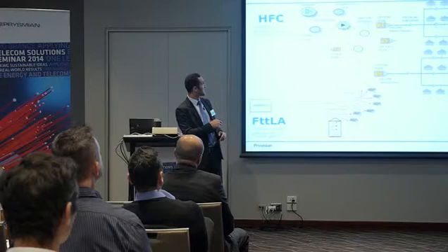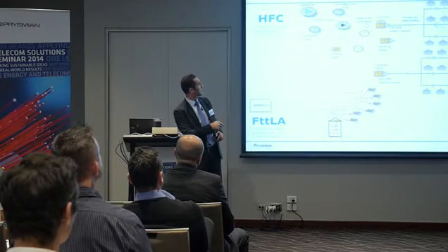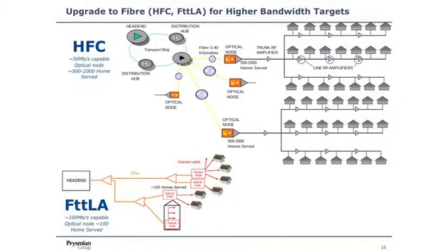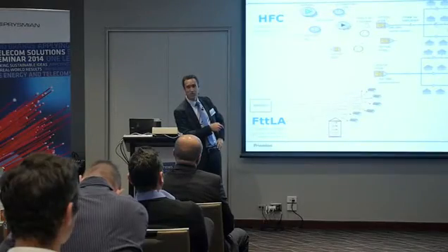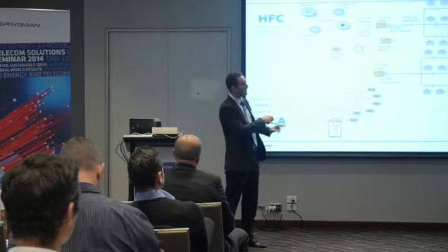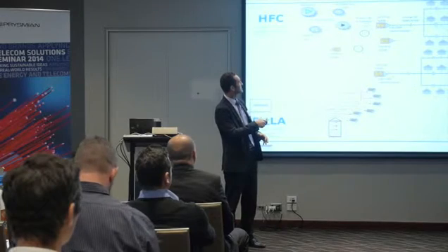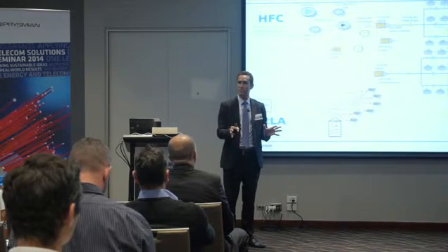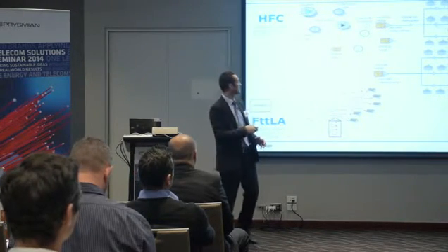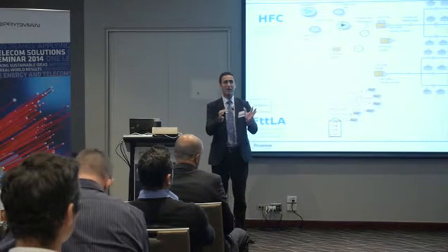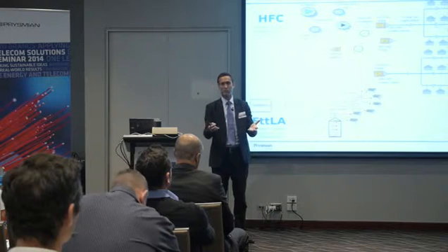30 megabit per second, and typically you have the head end, either directly or through a hub, connected to an optical node. So between the head end and the node can be between 5 and 40 kilometers of fiber in a cable. And then, starting from here, you switch to the coaxial world, and you can serve 500 to 2,000 homes. This area of homes served is called a cell, basically. So basically, you can serve 500 to 2,000 homes with 30 meg capable broadband traffic.